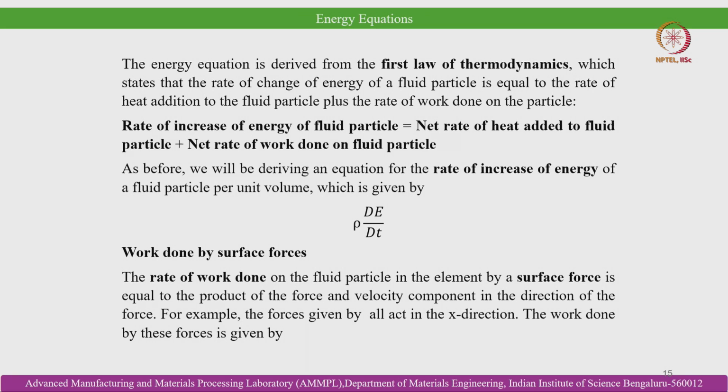The energy equation is derived from the first law of thermodynamics, which states that the rate of change of energy of a fluid particle is equal to the rate of heat addition to the fluid particle plus the rate of work done on the particle. So, the rate of increase of energy of a fluid particle is equal to the net rate of heat added to the fluid particle plus the net rate of work done on the fluid particle.